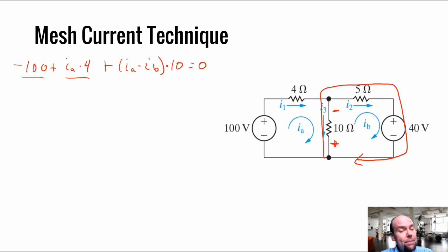You'll notice that's the opposite direction of the voltage drop for the previous version I did, because for the previous version, my loop was coming down at the time that it got to that point. And in this version, my loop is going up at the time I get to this point. So you might immediately recognize that this voltage is probably going to be the negative of the previous one, and that's true, but I can think about it a different way. I want to find this voltage as labeled, and if I want to use V equals IR, I need to have the current flowing into this positive terminal.